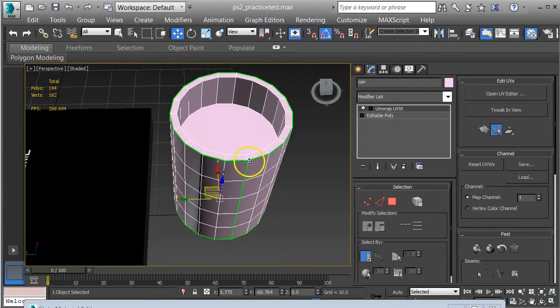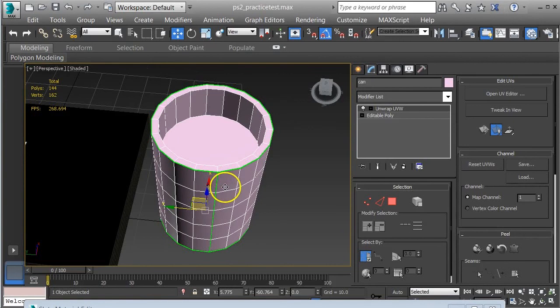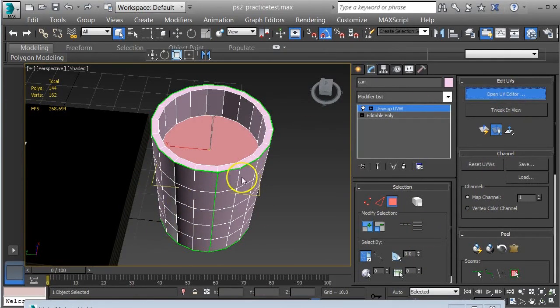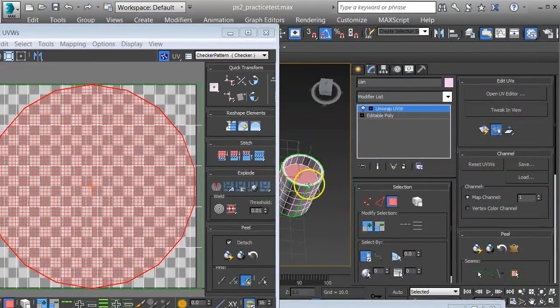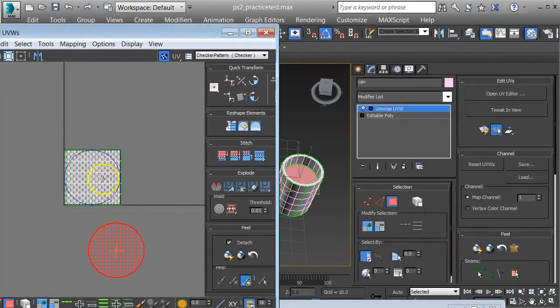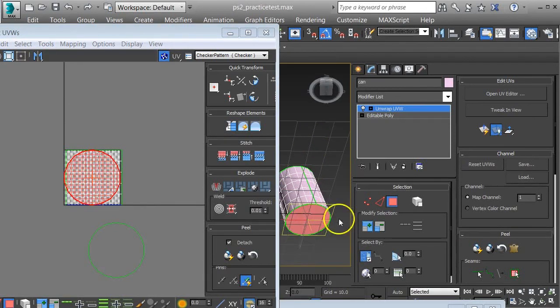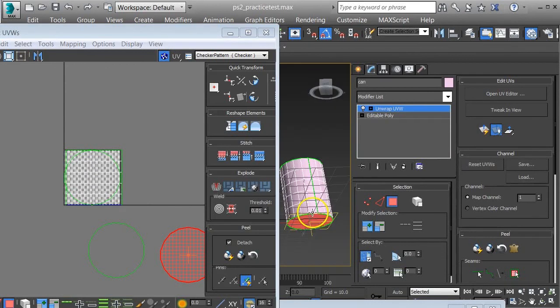That's going to put our seam almost at the front where we want it. So we can go in here and look at our UVs. When you have something flat like that, it looks like it already separated it out for us, but you can just simply do a quick planar map, separate it out, quick planar map that piece, the bottom.